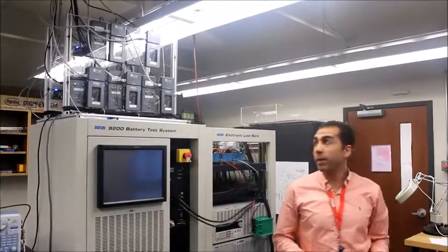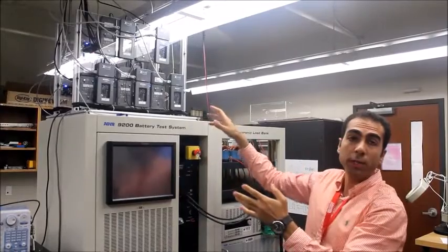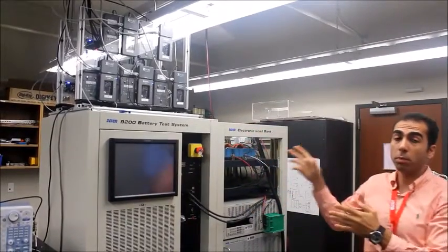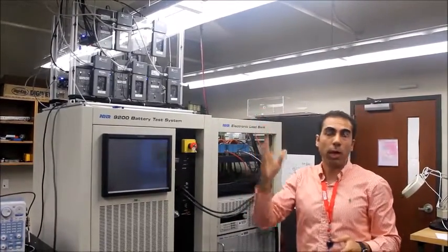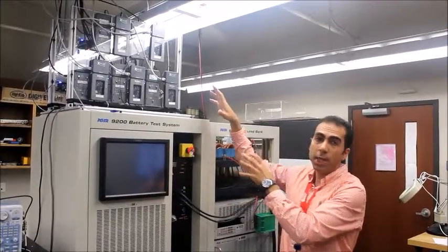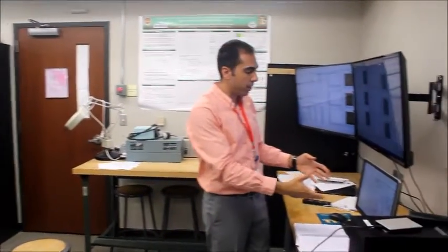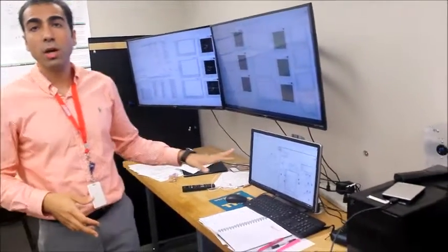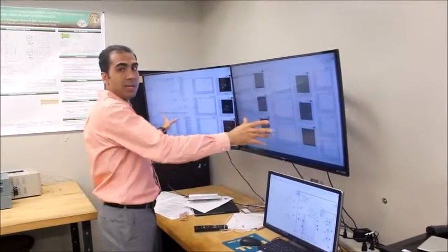Let's go back to the experiment. In this part of the lab, you can see 15 MyRIOs, real-time NI processors. So I have already imported data in 3 MyRIOs for islanding condition, fault, and load switching. From here, the data are sent to the layout I have already designed in LabVIEW for each condition. So I'm considering 3 conditions for now, like I said, islanding, fault, and load switching, and I can see the results in these 2 monitors in real time.